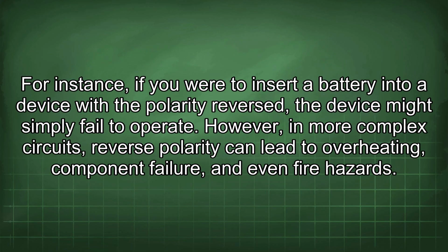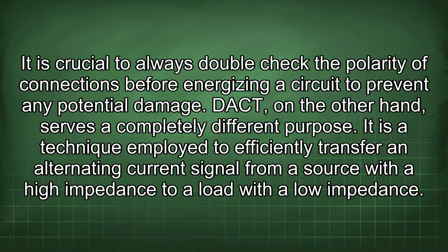For instance, if you were to insert a battery into a device with the polarity reversed, the device might simply fail to operate. However, in more complex circuits, reverse polarity can lead to overheating, component failure, and even fire hazards. It is crucial to always double-check the polarity of connections before energizing the circuit to prevent any potential damage.